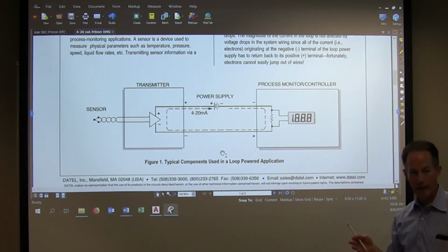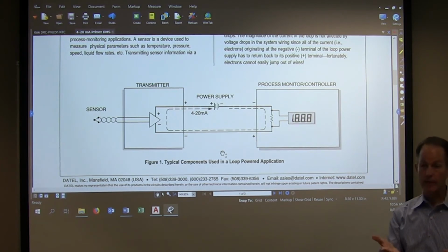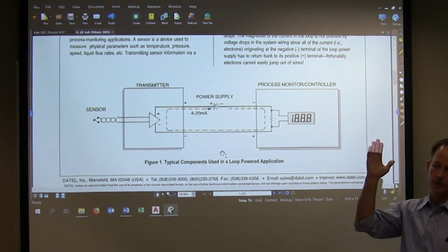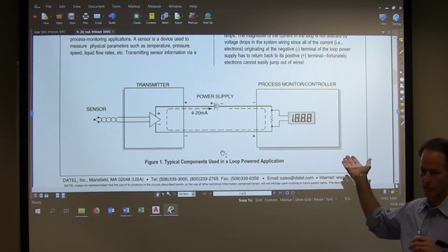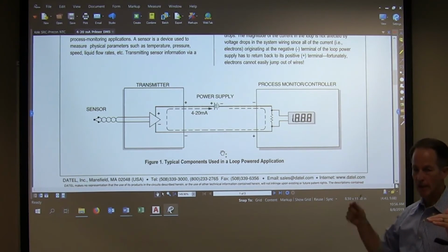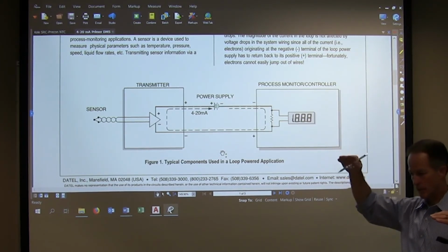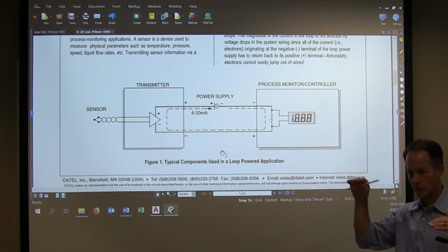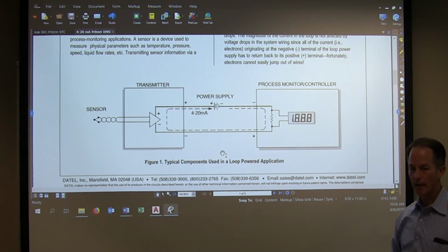Now, we don't always have a way to do that, but if you have a VFD, that's doable. Say the VFD is all the way at 100% and you're doing everything you can and you're still showing 17 volts, then you slowly bring the speed down on the VFD and you'll eventually see that thing drop off of wherever it was locked on. And so then, okay, I may be browning out on that or not have enough voltage on my power supply.